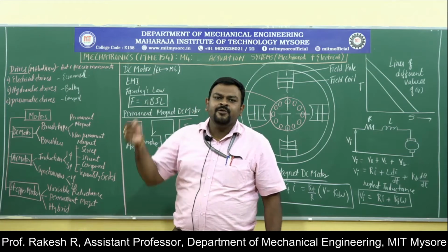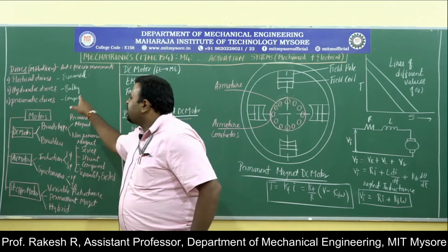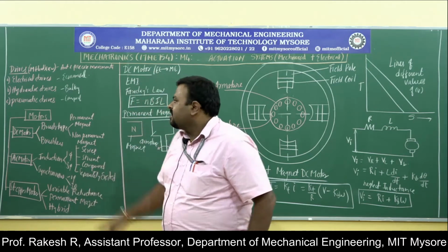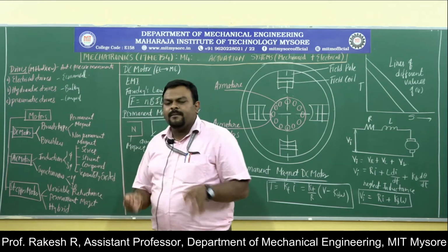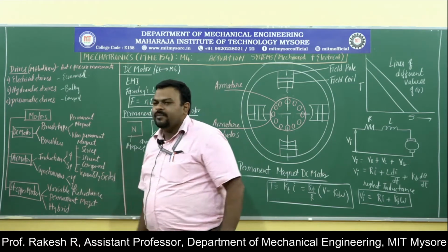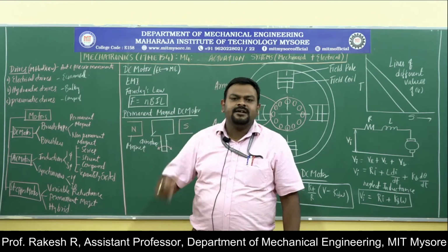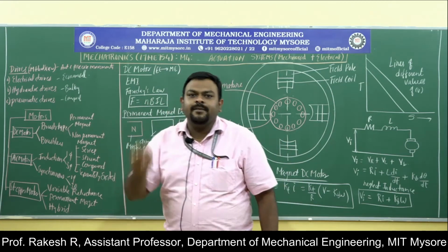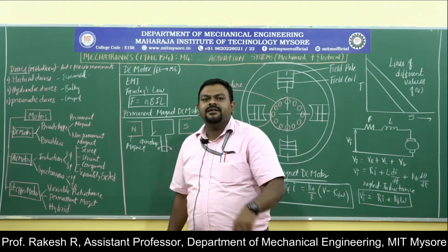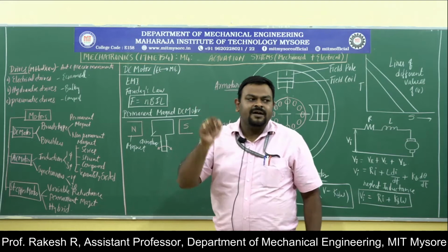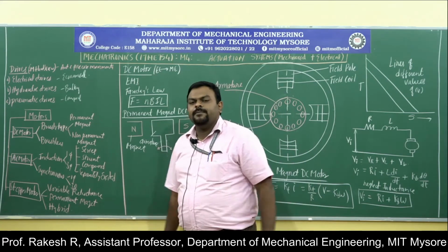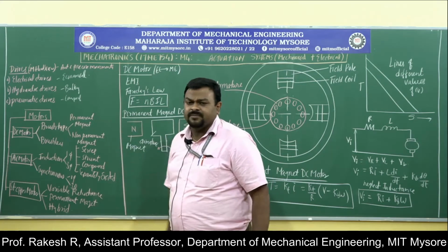Whenever we require a huge load to be lifted, in those cases we will be using hydraulic drives for the highest torque. And pneumatic drives are almost compact in nature, compared to hydraulics, whereas the cost of the pneumatic system will be slightly greater than electrical because we are using a compressor. That compressor will be a separate unit and it will have a reservoir in order to store compressed air. So these are the limitations of each drive, and depending upon the application, the drives are chosen.